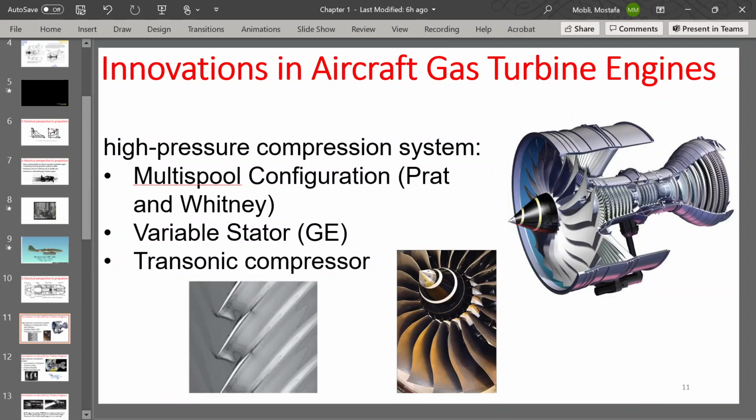How would it minimize drag? What will happen? Let me rephrase the question. What will happen to the stall of these blades? Because the air on the blade itself, the jet engine itself, can stall as well. It is not just the wing, right? What will happen to the stall of these blades when we are changing the angle of attack? I'm specifically asking about a stall.